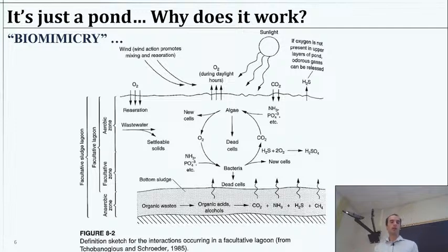It's not a complete BOD removal, but we should have a net discharge of some CO2, especially during the night, and some sequestration of carbon in general, probably organic carbon. That's going to be a lot of what you dig out whenever you do have to get rid of the sludge. Okay, so there's going to be some combination there, some balance, but that's all part of the scheme. So if things are going well, you'll have the algae producing oxygen during the day. They are consuming it during the night, just like all the other bacteria. And so you'll have these processes at some level.